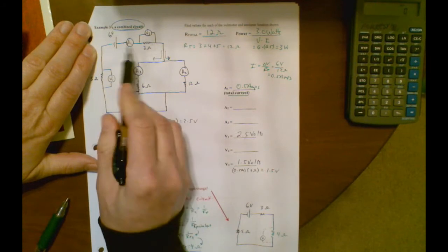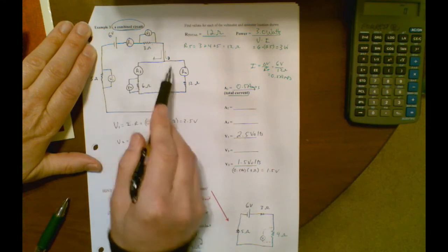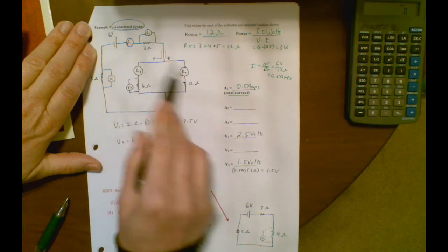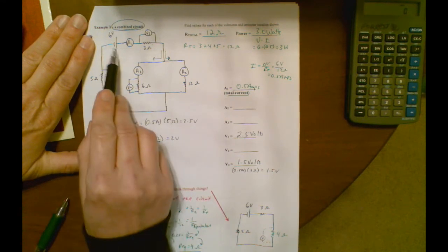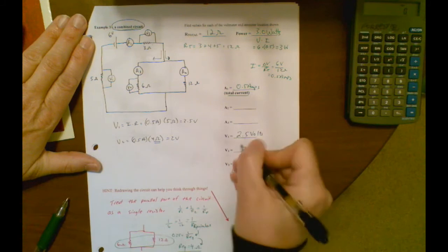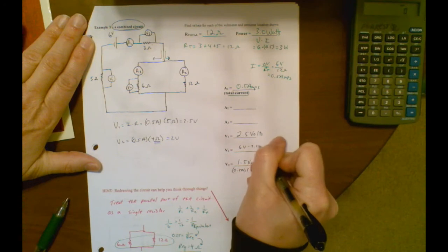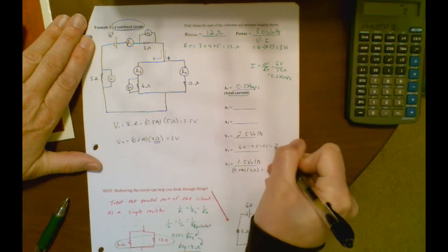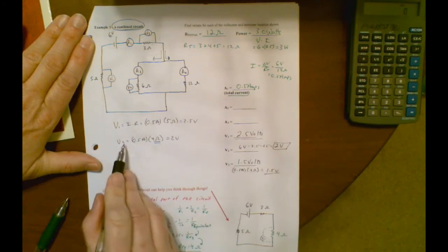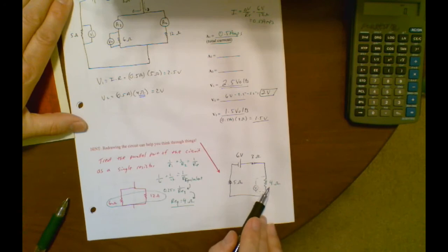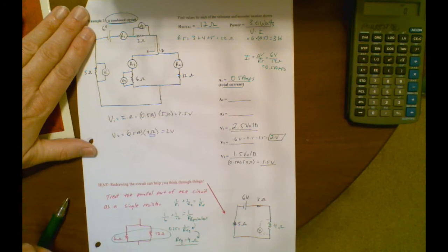And so essentially I've got 6 volts here, subtracting off 1.5 volts here, subtracting off 2 volts whether I go this way or this way, subtracting off 2.5 volts there, means I'm down to 0, which agrees with what I've got, which is a 6 volt potential difference. So I could say 6 volts minus 2.5 minus 1.5 will give me 2 volts left across this part of the circuit. So like I said, you could do that by looking at this equivalent resistance, or you could realize that the voltage that's left has got to be 2 volts.